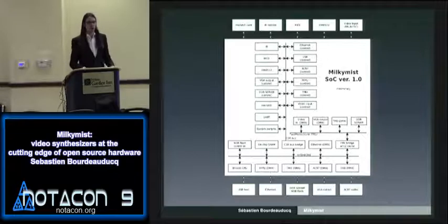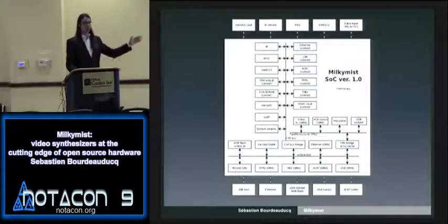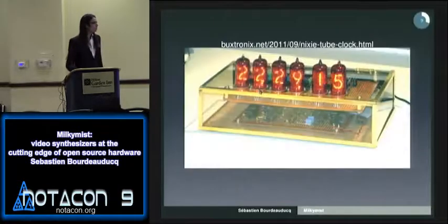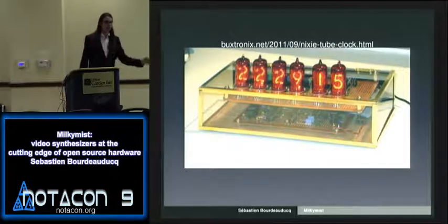It means texture mapping unit. It is a bit more than texture mapping, but that's basically when you are drawing some polygons in OpenGL, and then your graphics card takes care of it, and the TMU implements a subset of OpenGL. So we developed all this as an open source licensed system on chip, and now comes the question, how do you do such a thing? Well, it's basically just logic design.